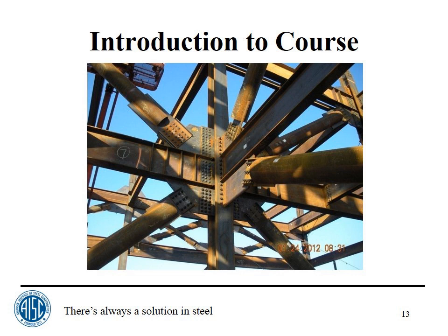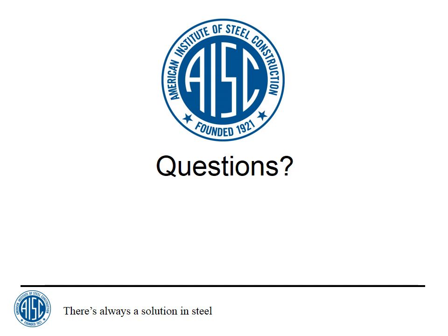Well, for instance, if you had a connection to a column web and you had a beam that was laid on its side so that you're connecting to a web instead of a flange, you wouldn't have any couples with the KISS method. I would say you would probably come up with pretty much the same design for both of them. I don't know that I've ever come up with a case where the KISS method was more economical, but I think that there might be some cases where it's really not that bad.